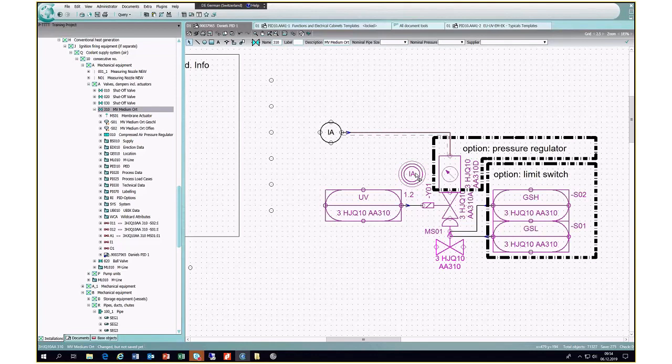These are just instrument air symbols that we have on the drawings, just to say where the instrument air is. Because the instrument air, like I explained one time, I think it was in the second module, we don't draw all those pipes on the drawing. I'm not sure, do you do that in Japan as well? Do you draw the actual pipes for instrument air on the drawing? Or do you just sort of make symbols like that as well? The PID?